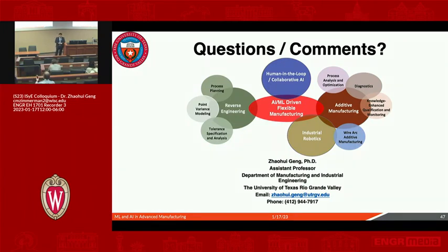Yeah, reverse engineering is very popular for defense-related applications. Defense manufacturers generally have some very old technology, dated several decades ago, but they do not have access to the original design. If a part is broken, how can you remanufacture it without the design? Or they may want to do part consolidation. For example, with two sub-assemblies, because of additive manufacturing, rather than making sub-assemblies, we can directly consolidate them to fabricate a single part. I think GE is doing that right now. Reverse engineering tells how to find the original design, and based on the design intention, whether we can consolidate those.